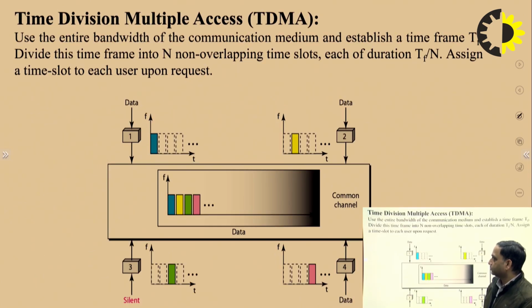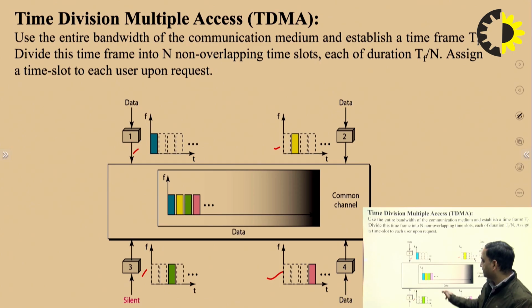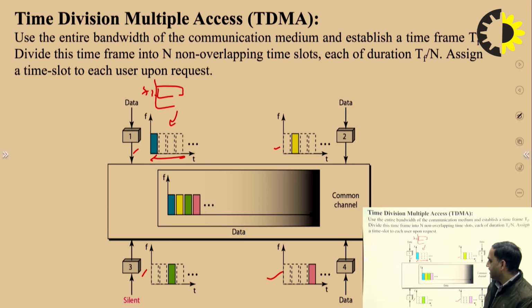When we talk about the time division multiple access technique, different users transmit their signals at different time slots. We can see in this diagram, in the previous diagram we were using frequencies, but in the case of time division, this complete frame of time is divided into subframes, and subframes are divided into slots, and each data or user source will transmit its signals at the different slots.